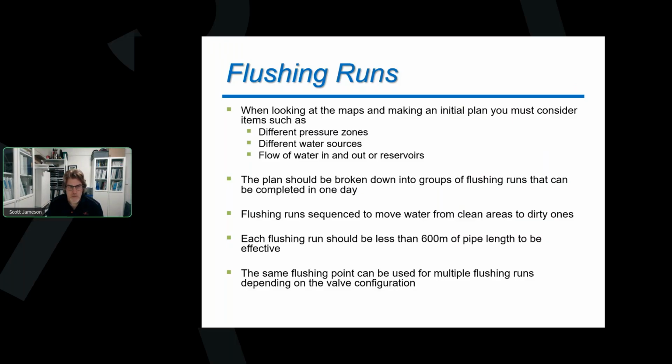Now, the other one we're going to look at when we're doing our flushing runs is we want to break down our system into very small chunks, right? We want to look at how much I can reasonably achieve in one day. How many flushing runs? And this might be limited by the size of your community.